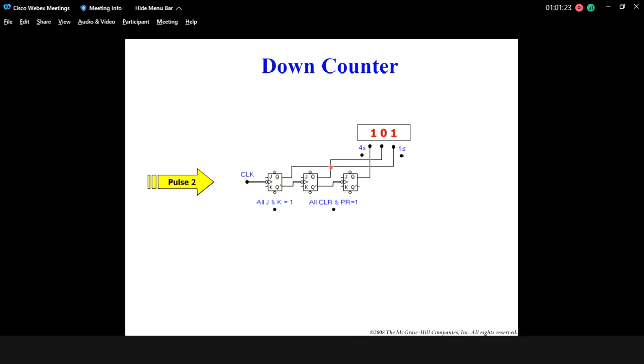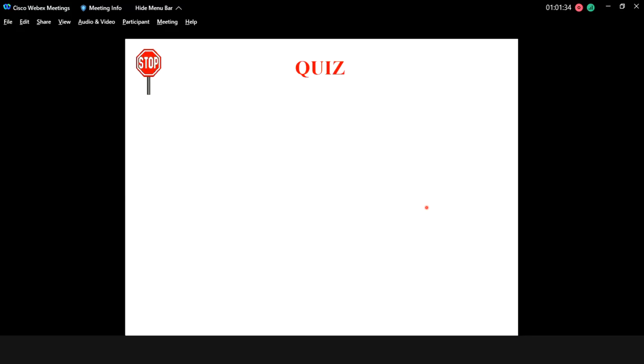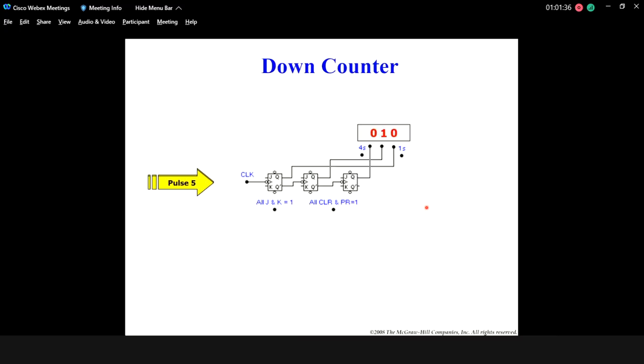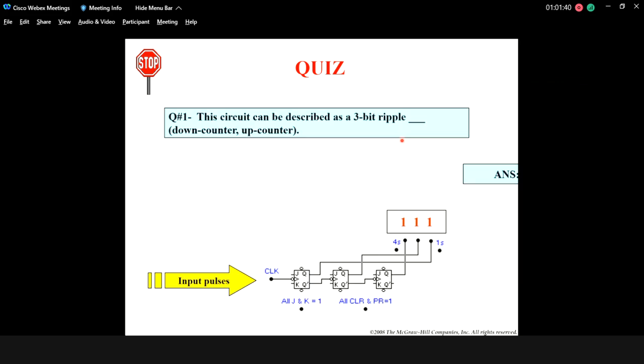From 1 becomes 0, and then this one is 1, already at high state, okay? Goes down, becomes 100, and continues until 000, okay? When 000, it becomes 1 again. But that one is just a countdown, not self-stopping, okay?